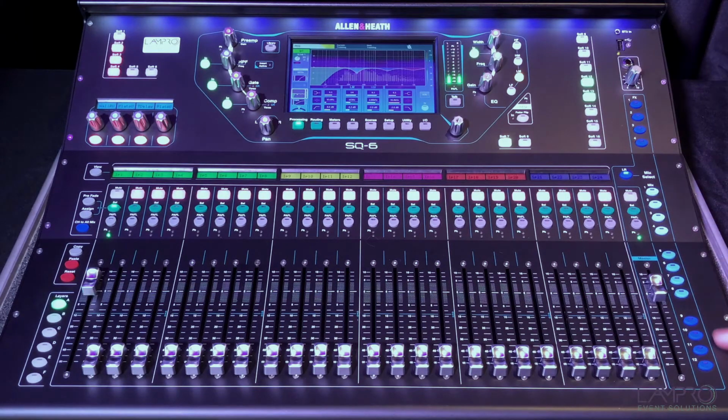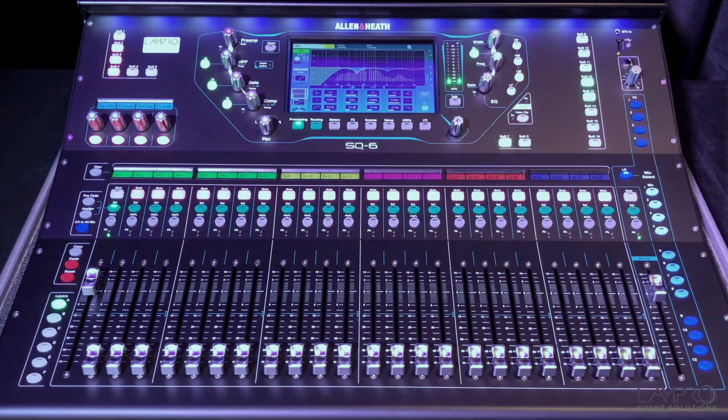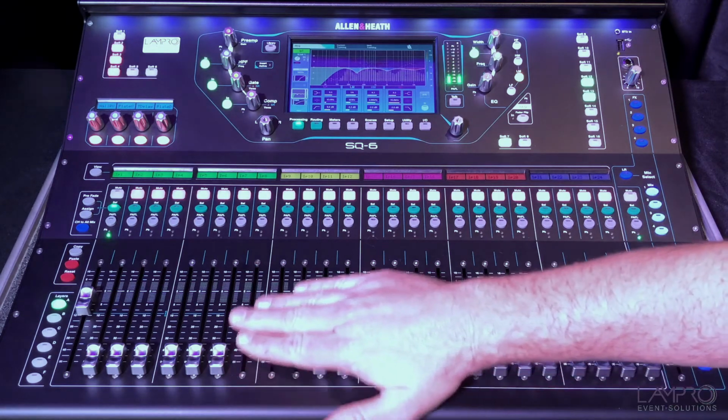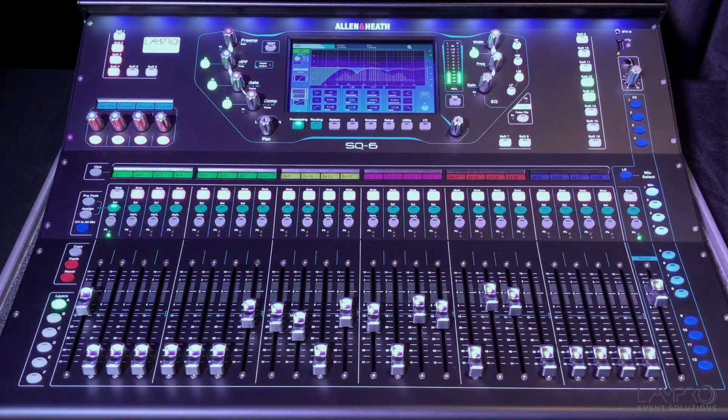The 12 mix buttons are used as aux sends that can be used in pre- or post-fade mode to send any of the channel's audio signals to the assigned mix output. That can be used with stage monitors, additional speakers, or recordings. You simply select the desired mix and send the channel's audio levels with the faders to the selected mix outputs. The master fader on the right will act as the aux master.